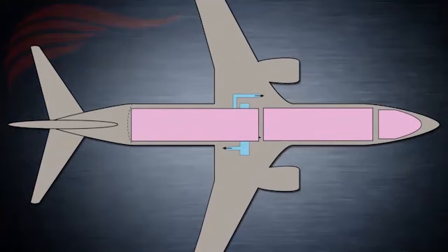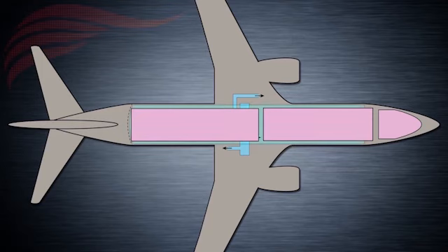Essentially, the air conditioning system performs the following functions. It produces fresh conditioned airflow for air pressurization and ventilation, controls the flight compartment and passenger cabin temperatures, recirculates around 50% of the cabin air for ventilation purposes, and removes unpleasant air from lavatories and galleys.